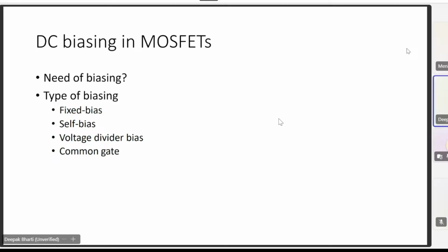For example, we know R, L and C are examples of passive devices. We need not turn these devices on separately in order to show resistive, capacitive or inductive behavior. As soon as they are connected in the circuit, they display their normal behavior. But active devices, for example transistors, need to be first turned on in order to operate with transistor behavior. That is the basic reason why we bias the transistors.